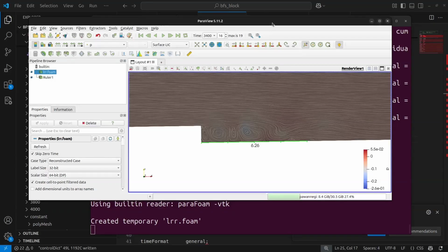The fastest model is the one equation model, which is present in OpenFOAM. There is a zero equation model as well, but that you have to implement on your own. All these models, which are based on the Boussinesq approximation, assume isotropic turbulence.